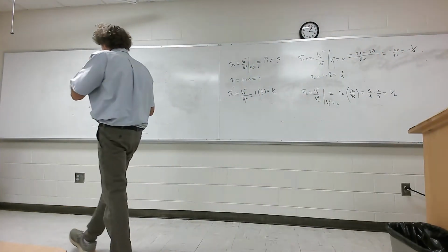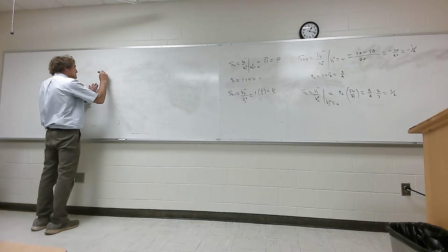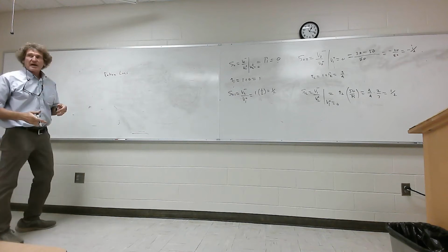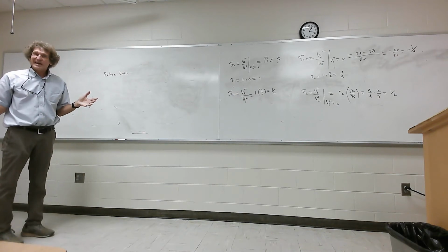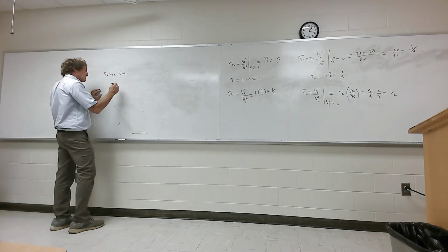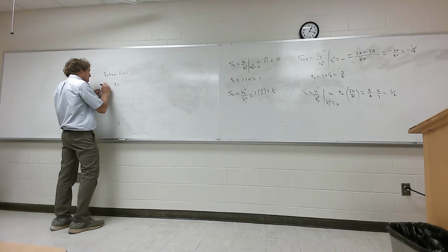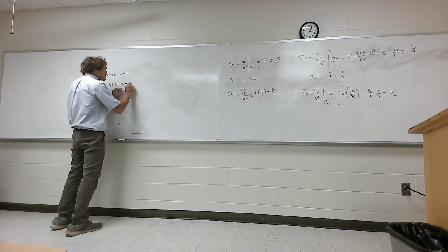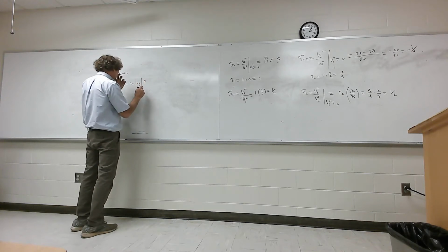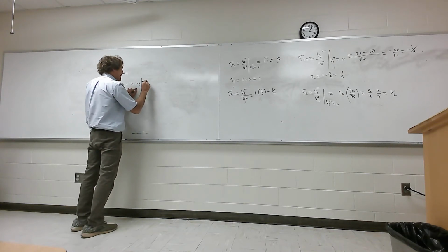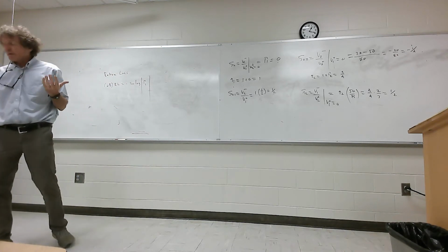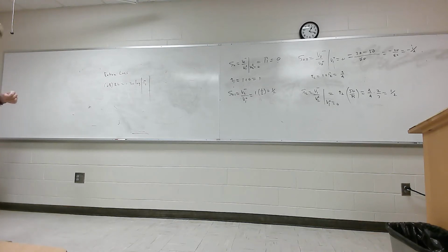When you talk about return loss, this is just a measure of how good a system is operating. You'd like to have really no return loss. That's the idea, no reflection. So what is it? Well, the return loss is in dB, and it's minus 20 times the log of the magnitude of the reflection coefficient at that port, which would be at port i. So the return loss at port 1 would just be minus 20 times the log of the magnitude of the reflection coefficient at port 1.